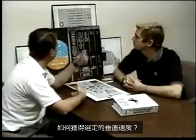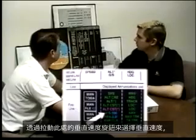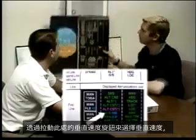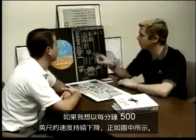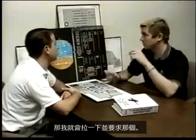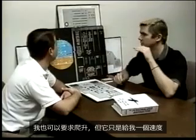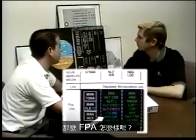How would you get a selected vertical speed? Selected vertical speed is done by pulling the vertical speed knob here. And what that gives you is a reference to a vertical speed. If I want to constantly descend at 500 feet per minute, as this indicates, then I'll pull and ask for that. I could ask for a climb as well, but it's just giving me a speed or a vertical rate of climb. What about FPA then?